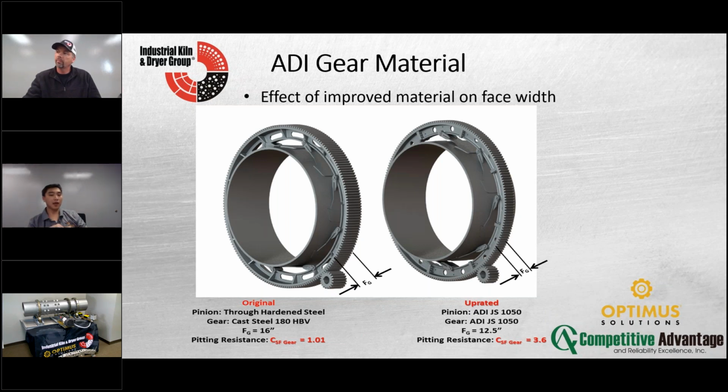You can say have a gear with this particular size and reduce it and have, say, an effective equivalency on the grades, on the hardness, on the strength, and say, hey, we can make it smaller and it has the same effect, right? So that's what a lot of people are always like, well, if you keep making it smaller. Well, my view is, why not keep it the same sometimes? If it's 16 and you keep it at 16 inch on the face width, it's effectively much stronger.